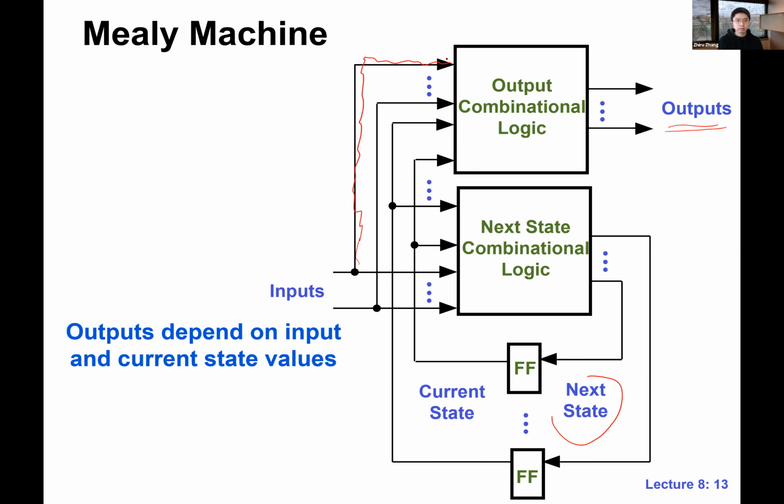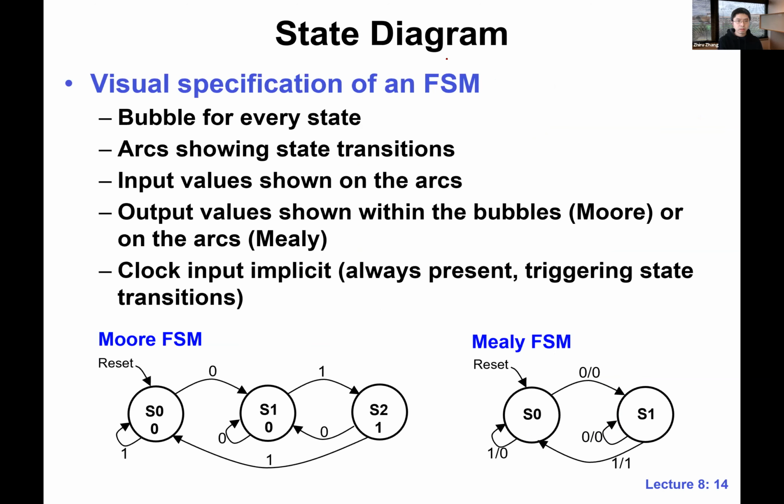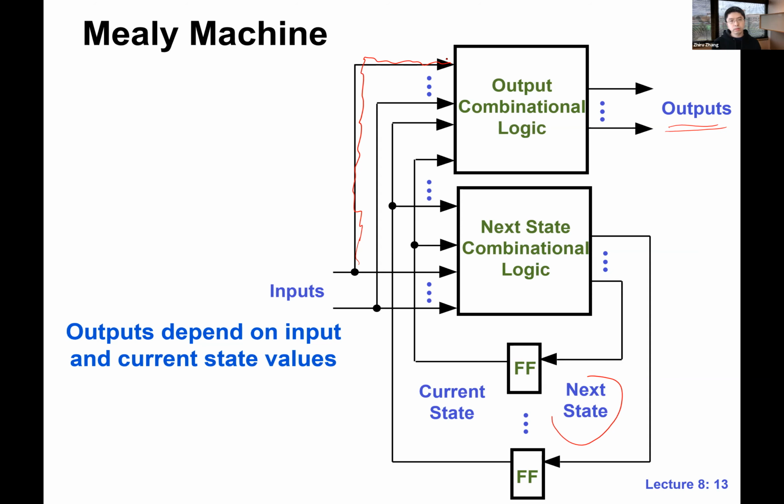All right. So this is one way to look at this, the more hardware-centric way to look at the Mealy machine and the Moore machine, right? So we basically decompose the combinational logic into two parts, right? So later on, when you guys write FSM, that's going to happen in lab 3, you will need to design an always block, right? One always block for next state logic, and another always block for output logic. Okay, both are conditional.